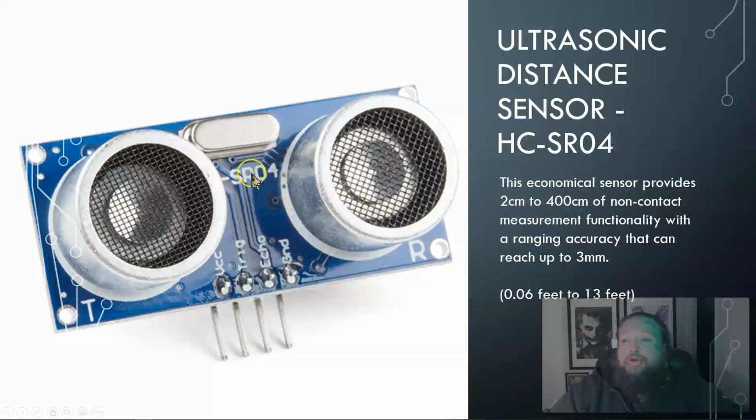Most times for the ones working with Arduino, you'll see the name on the front or back. When you look at a sensor and you're not sure what it is, the kits have pictures, but most times there'll be indicators or markers of some kind of name that you can then search and find a whole bunch of other examples. So you have to be careful that the rest of the work I'm talking about is specifically this HC-SR04 sensor. If you see other ultrasonic sensors, it may be a similar idea, but there are different things you need to do to write the code for it.